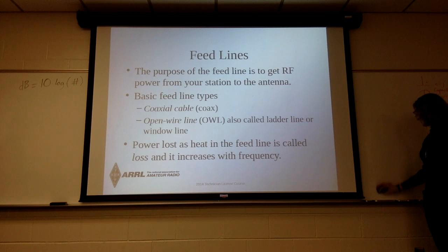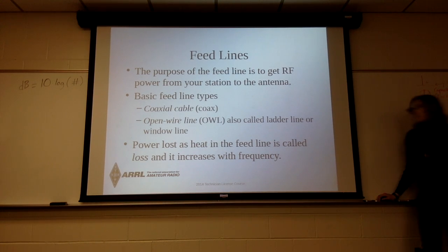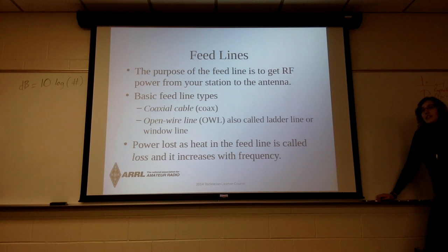So feed line is not perfect. If you use feed line, there's going to be some power that's lost in the feed line itself, unfortunately. And that increases with your frequency. So if you're using a feed line at like 1 megahertz or 2 megahertz, you might not have a lot of loss. But if you moved it to 200 megahertz, you could have a whole bunch of loss for the same